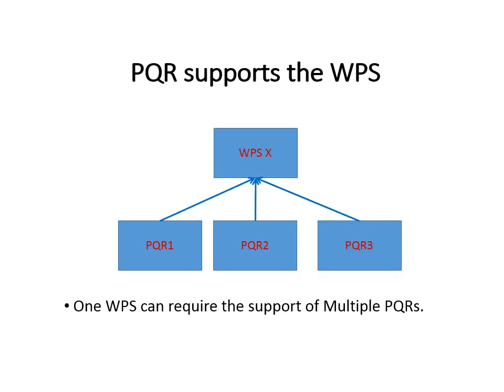And as I said before, a WPS to a PQR is not a one-to-one relationship. Sometimes you might have 3 PQRs supporting one WPS. Let's say I started off with A36 carbon steel base material, and I welded it with E7018 low hydrogen electrode, and that was my original WPS.